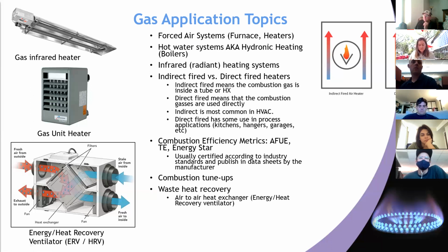They actually produce such a high intensity heat that it transfers directly through electromagnetic radiation to land directly on a surface. So they really aren't heating and transferring heat through a medium. They're doing it through an electromagnetic wave. And so there's no transfer to a medium, and then from the medium, it's just directly to the surface that is being warmed.